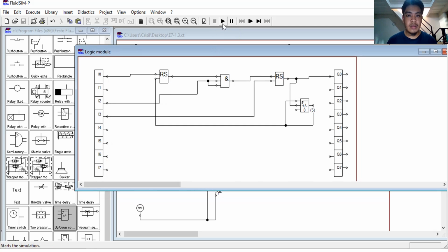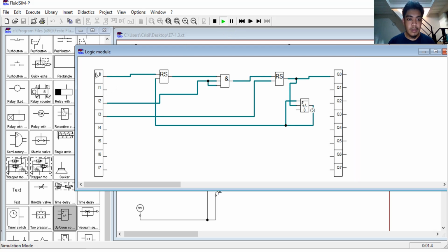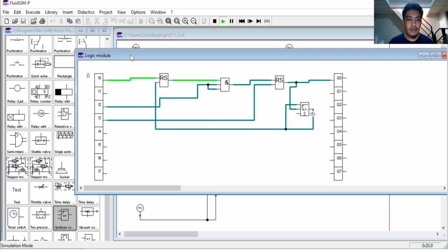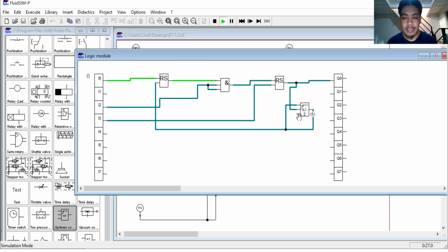Now, this is our logic. So let's give it a try and press. Since this is normally open, we consider that. Then as you can see, there is an expanding, and this here expanded, then retracts, then expands, then retracts. So in our wiring, this is automatically on and off. But as soon as the pulses reach 5, it will be completely cut off.